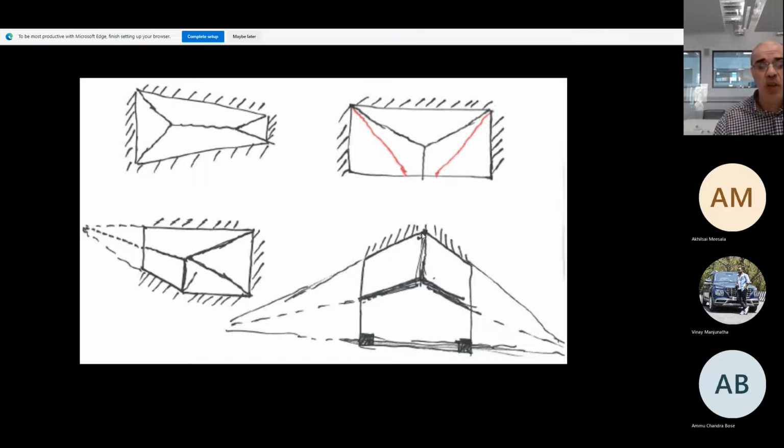So basically, what you do then, you take the axis of rotation about the columns, extend it. You take the axis of rotation of this side, extend it, and you take the axis of rotation, which is this side here, extend it, and then it gives you the points here of intersection, and the yield will start with the maximum curvature, and then you join to the points of intersection of the axes of rotation. Is that clear? So it's very easy to do.